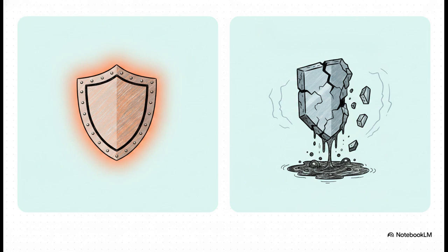The chemistry here is wild. When iron and sulfur are heated together without any intervention, they naturally bond to form a compound called iron sulfide. Let's compare these crucial melting points. Pure iron melts safely and strongly at 1,539 degrees Celsius, but iron sulfide is incredibly weak, melting at just 1,200 degrees. That means that inside a hot, solid piece of steel, microscopic pockets of iron sulfide will melt and turn to liquid way before the rest of the iron does. These tiny liquid pockets create massive weak points, literally causing the metal to tear itself apart under industrial heat.